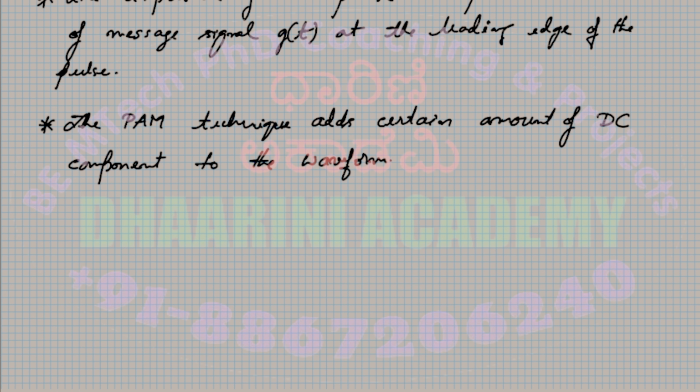But there is a major application of this technique: you send this signal, doing modulation plus multiplexing, specifically called time division multiplexing. PAM is widely used there, though there is another concept, a bandwidth requirement. The bandwidth required to preserve this pulse shape is normally more than the message signal bandwidth. The message signal will have a certain amount of bandwidth.